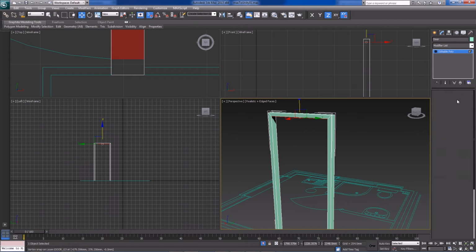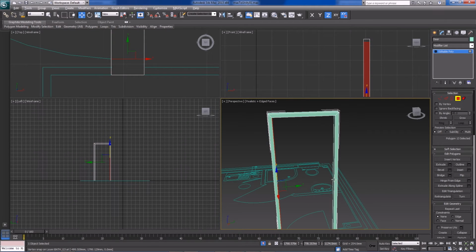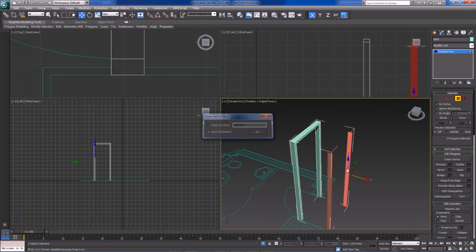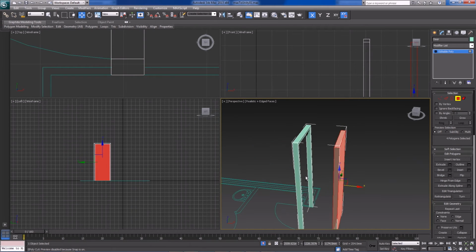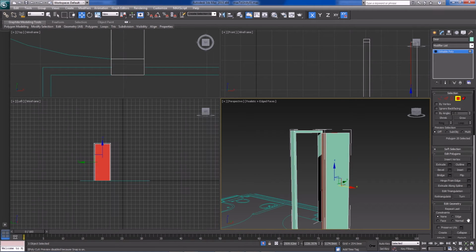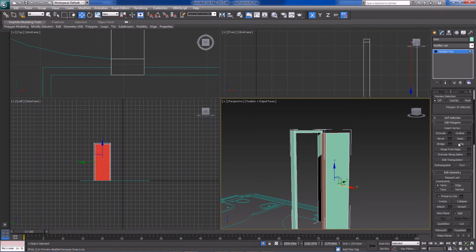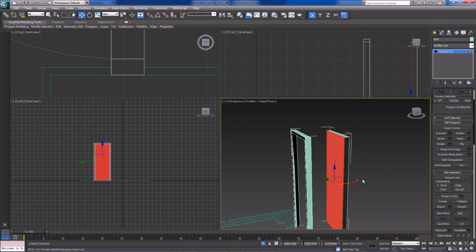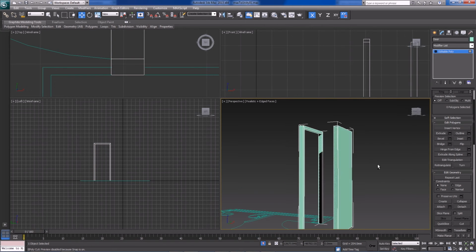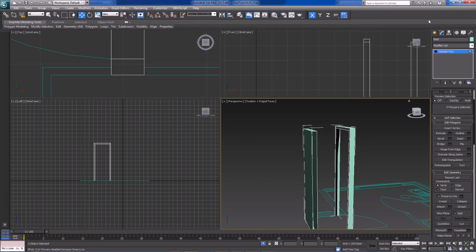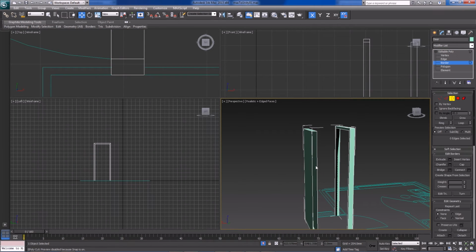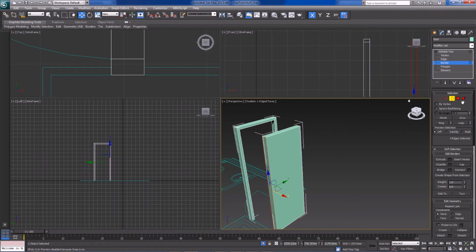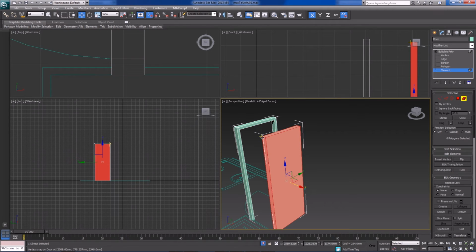So let's clone these two faces, because these are the two faces that capture where our door needs to be. And we can just bridge these. Yeah, there we go. Now this edge, I believe, is flipped because it's facing the wrong way. It was facing inward. So if we flip, it should turn lighter. No, I was selecting the wrong face. Okay, when we bridged, I see what's happening here. It actually removed these faces. So we can just quickly cap these. And now we'll have our door object, which is made to measure exactly. So let's just drag it in there.